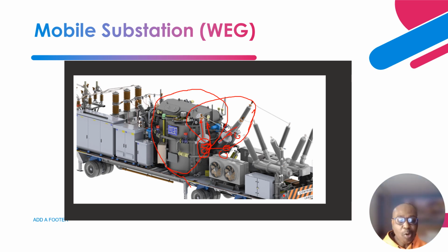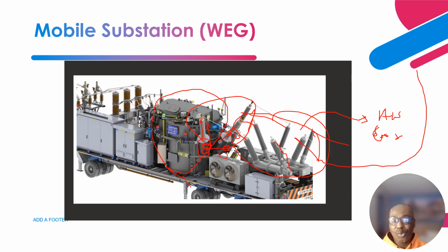Okay, so on this side, like I had indicated, you need a switching device. It can be an air insulated breaker or gas insulated switchgear. In this case, it's a gas insulated switchgear. So you have an input coming in, the line side coming in, and an outgoing side that goes from here to the transformer. This one is integrated to your tower structure through a drop-down conductor, let's say 115 kV or 230 kV or 345 kV.